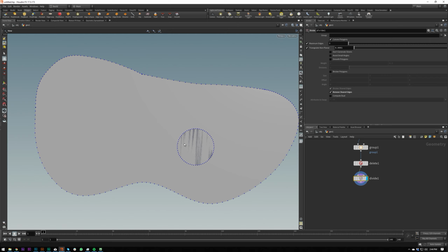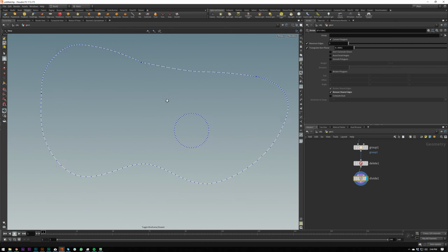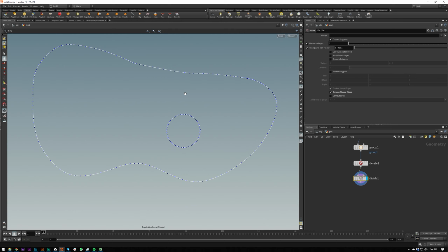So just so we can see what the spline looks like, I'm going to click escape if we've got our cursor up. Make sure you're doing this over the scene view and click W, and that will put it in wireframe mode up here. By default we were on smooth shaded, but we wanted wireframe so we can see the spline. And then we don't have to see this monstrosity at the moment. We'll come back to this, so trust me guys.